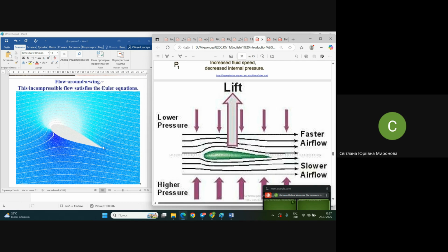And in order to meet, those that pass along the bottom have a shorter distance to pass. And those that go along the top surface, due to the non-symmetry of this airfoil, or due to its changed position, like you see right now, that it's rotated with respect to the horizon of the flow, because of this they are distorted, and here is the longer path to pass. Quite clear, the longer path in the same time means that here we have higher velocity over the profile.